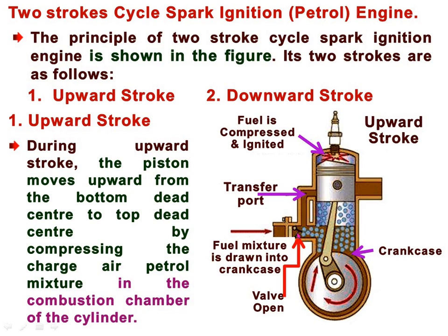See, this is the inlet valve or inlet port, through which the air fuel mixture is introduced into the crankcase. The air fuel mixture is drawn into the crankcase through this port.